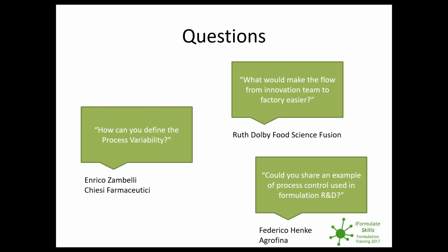Because in reality, if the product has got to the end and it is outside the upper and lower specification limits, or if the process capability is under 1, that means product is falling outside those limits, then it is already waste. And there's really nothing we can do unless the organization has the opportunity to rework it.